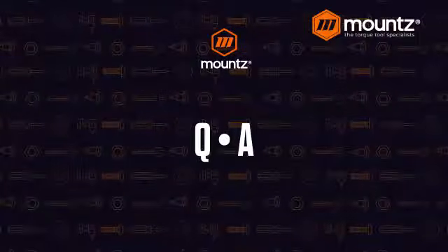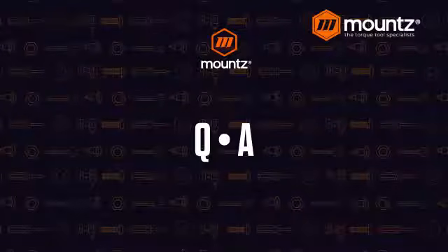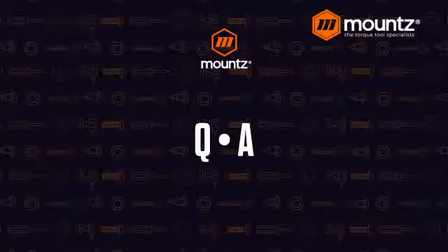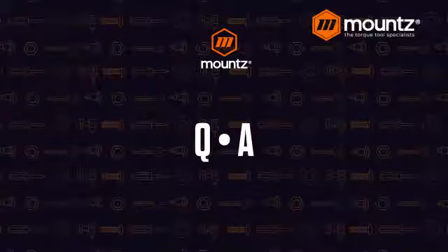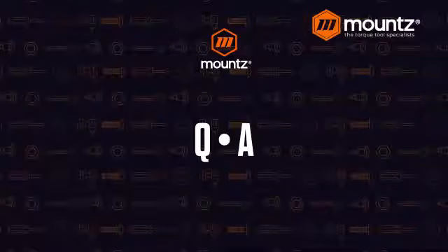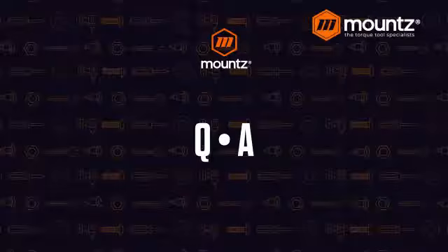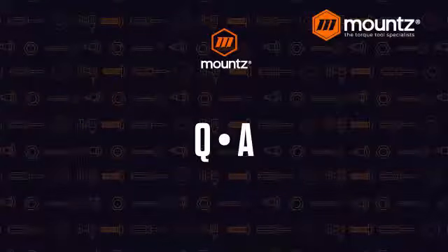We have a couple questions to kick it off here. The first one was, for the torque verification process, is there a recommended number of rundowns that serves as a benchmark? Typically, you want to do maybe at least 5. If the tool is not in use at the time, you're going to want to make sure that the tool has been exercised. So you'd want to run that down probably about 5 times before you do your testing, but it could be anywhere from 3 to 5, could be 10.